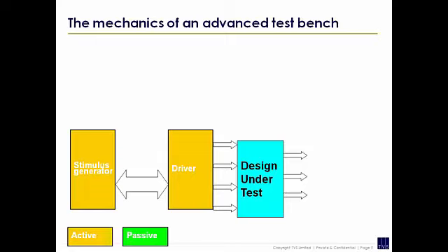Okay? Now the reason we have a driver here, because this is a level of abstraction. So let's imagine you've got an interface on your design, maybe an I2C interface. People are comfortable with I2C. So this is maybe an I2C interface here. What you want to do is send in packets. So at this stage here, you're sending I2C packets, and this driver says to send that packet in, I know what the protocol is. So it turns your I2C packet into the appropriate protocol signal wiggles here.